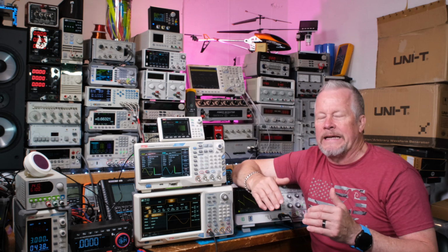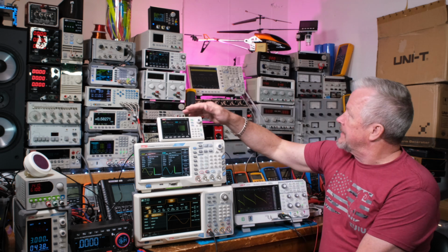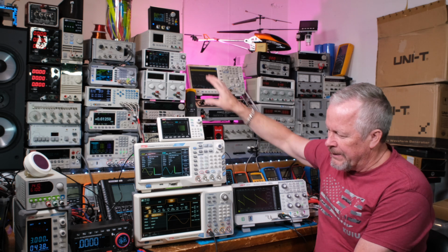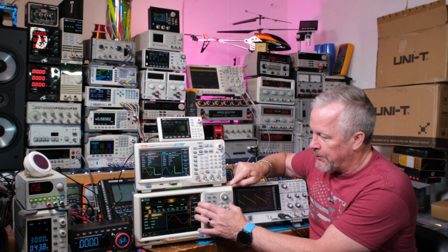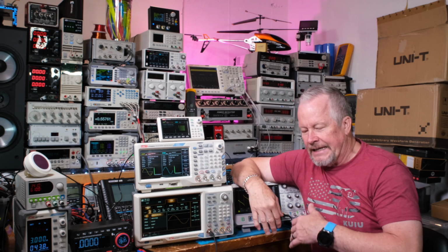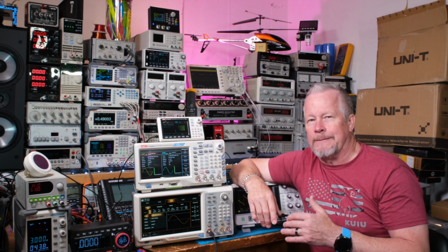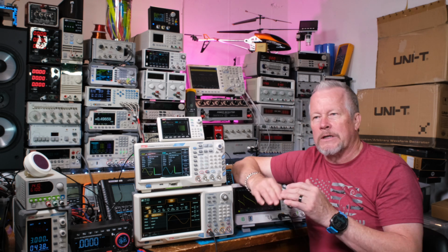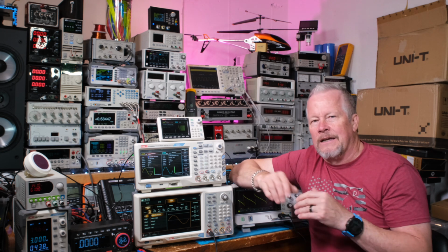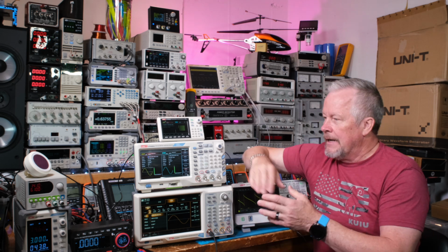So you want to have an analog signal, like perfectly smooth, right? So you go from 14 bits to 16 bits. And the rest of these generators, I believe, are all 16-bit. Now this guy here, channels 3 and 4, I believe, are 14-bit, and channels 1 and 2 are 16-bit. So 16 bits is another 4 times more resolution. It's like 65,000 little steps. So if you're looking at, say, a 1-volt signal, that's built with 65,000 little staircases. Crazy, right? Even 16,000 would be crazy.